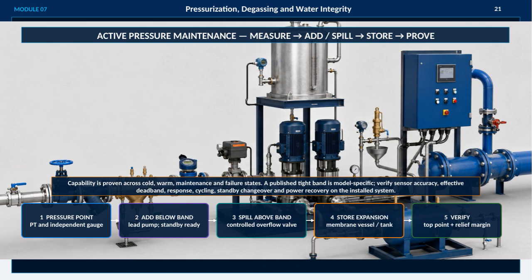This capability has been proven to work reliably across different conditions, including cold, warm, maintenance, and failure states. Remember, the specific tight pressure band is model dependent, so it's essential to verify sensor accuracy, the effective deadband, system response, cycling, standby changeover, and power recovery on the actual installed system.